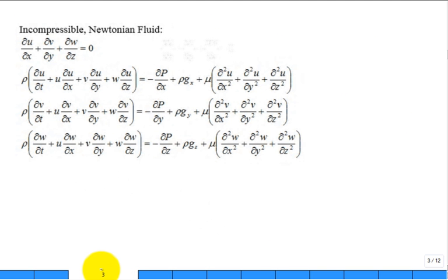So you can expand these, and they're in the equation sheet and textbooks, expanded in the Cartesian coordinate system. So this equation is the continuity for incompressible Newtonian fluid. Really, it's just incompressible. And then for a Newtonian fluid with that viscosity, you expand out the x, y, and z momentum equations, and you get all of these terms. And so it's nice to solve some problems where you would start out with a pretty large set of equations and then strike the zero terms and then reduce to a simple ODE maybe, and then solve that ordinary differential equation.